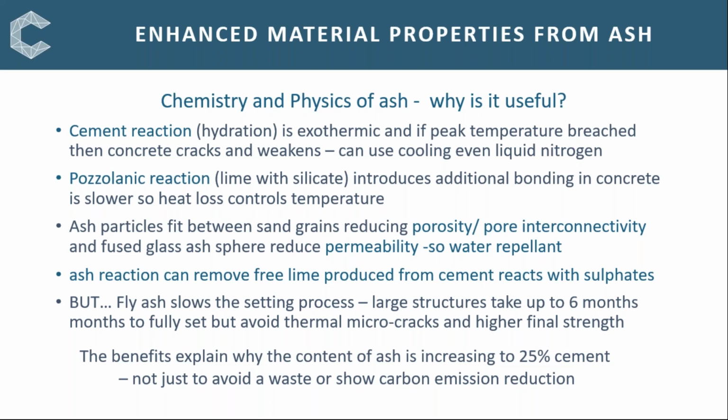India is trying to change the brick industry away from clay bricks to fly ash ones, as there are currently 100,000 clay kilns that are all fired 24 hours a day and require raw clay obtained from arable soils, amounting to around 5,000 acres each year. The switch to ash bricks would substantially lower the environmental impact and provide a more reproducible brick that doesn't need to be fired and has more strength.